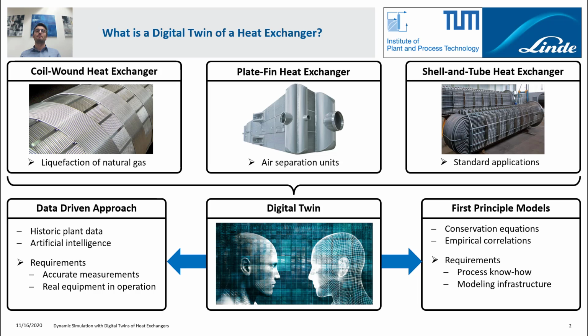the equation system. At Linde Engineering we now decided to go for the first principle model of a heat exchanger as the core component of our digital twin, simply due to the large amount of process know-how we have within our company. Furthermore, we would like to be able to extrapolate with our digital twin beyond the normal operating range of a process plant. And the purely data-driven approach of course is limited to this normal operating range as the data is collected in that normal operating range.